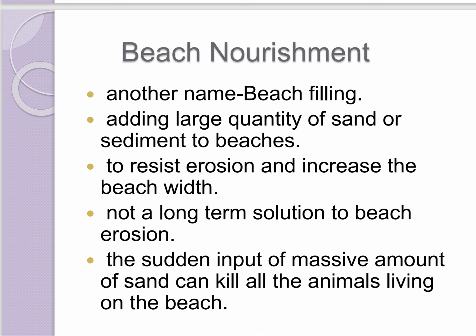So the next non-structural method is called beach nourishment. Another name is beach filling. It is basically adding a large quantity of sand or sediment to the beaches to resist erosion and increase the beach width. It is not a long-term solution to beach erosion. And also the sudden input of a massive amount of sand can kill the animals living on the beach.